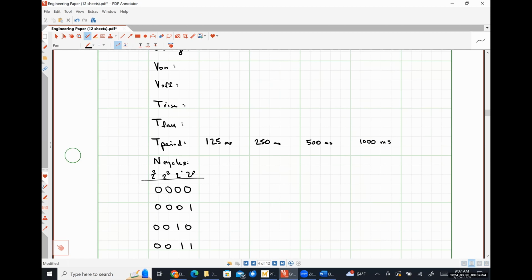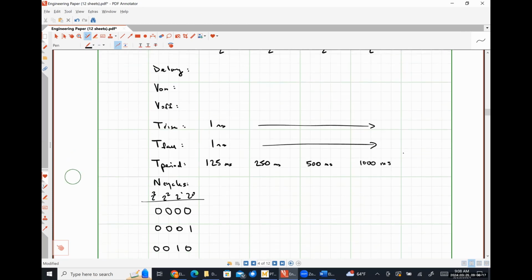All right, so our rise and fall times, that's just the time it takes to transition from 0 to 1 and from 1 to 0. So let's make that just incredibly short, like 1 nanosecond for everything. What do we want the voltage to be when our input signal is on or providing us our 1 volt? We're going to put ones and zeros in, and we're going to get 15 out, right? So V on is going to be 1 volt for all of them. V off is going to be 0 volts for all of them. If that's something that we control, I don't exactly remember.